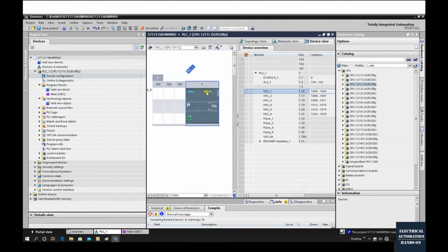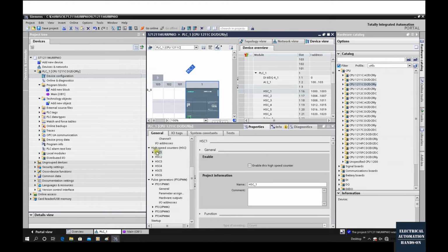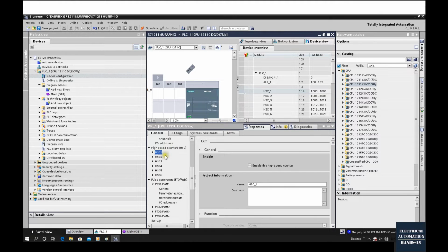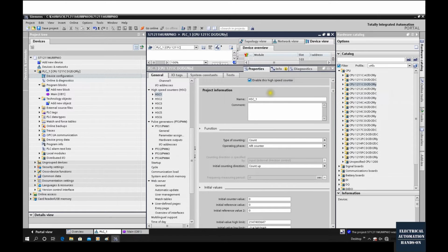Let's go to the system hardware properties. Double click this controller. Let's go to the High-Speed Counter HSC page. We can pick resource one. Actually, you can pick any of them. It doesn't matter, because it's flexible, we can configure which hardware channel belongs to which resource. This just represents the resource. Okay, so we can pick number 1 and check enable. Okay, we enable this resource.